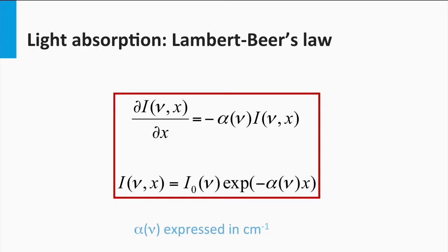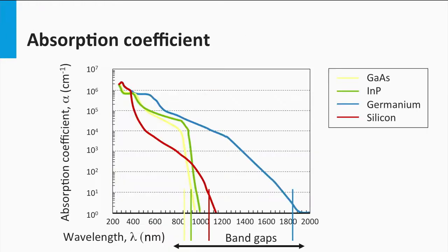For a solar cell, we would like the absorption to be 100%. In this condition, the absorber would be called optically thick. This means the transmission is 0%. From Lambert's law, it can easily be seen that this can be accomplished by either large values for the thickness d, so very thick films, or large values for the absorption coefficients. It is important to realize that the absorption coefficient for materials is not the same at every wavelength.